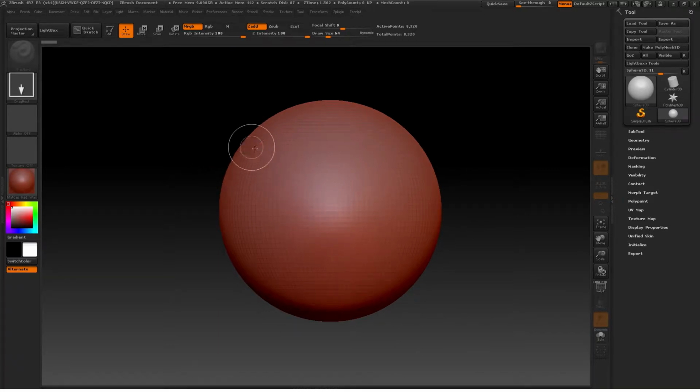The next thing we need to do when we place our sphere on the viewport is to activate the Edit mode in ZBrush. Here we have Edit Object, or you can press T on your keyboard. It's important to always have this option activated, if not, we can't work.